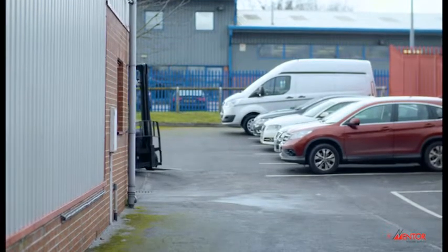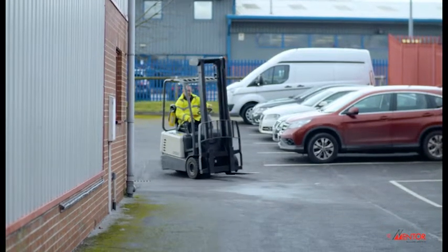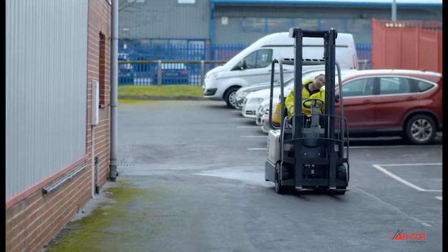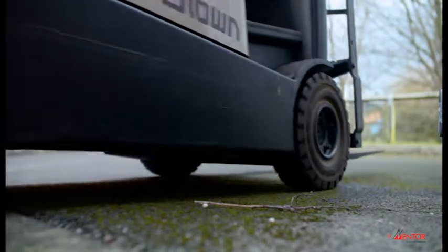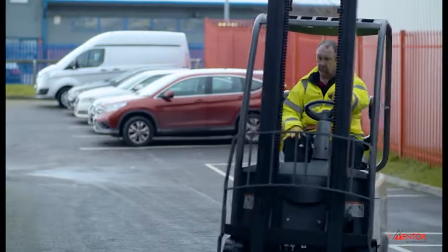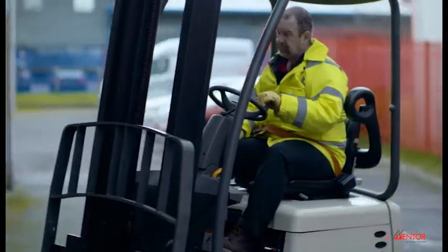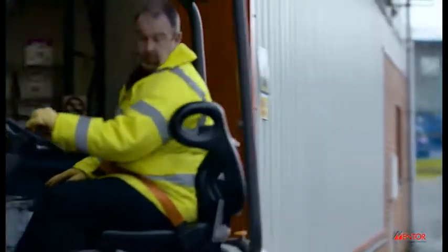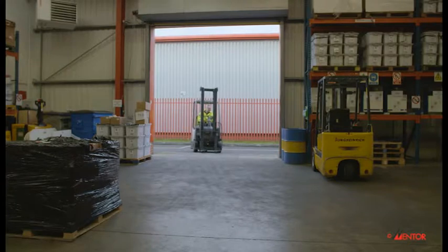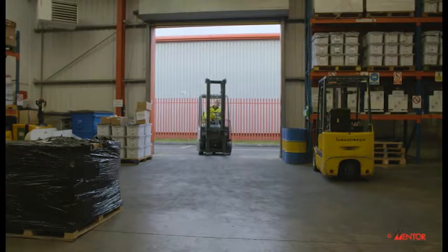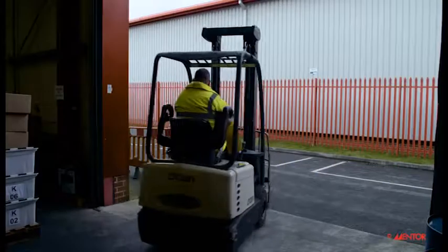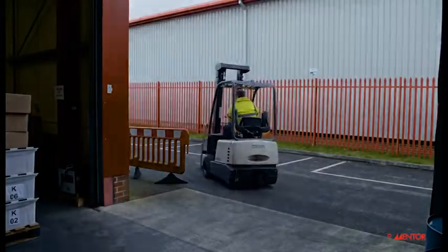Wherever you are operating a lift truck, you should always drive at a speed that is appropriate to the environment and conditions and according to the company rules. Increases in traffic, reduced operating space, visibility and ground conditions will all affect your conditions and environment, and therefore your speed should change to suit the situation. You should always drive at a speed that would ensure that you have time to safely react. Avoid fast cornering and harsh accelerating or braking. Reduce your speed and stay in control.